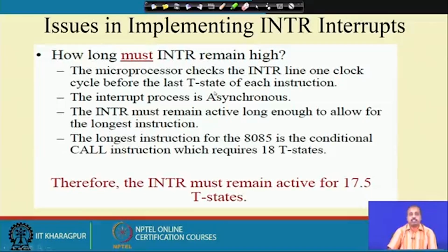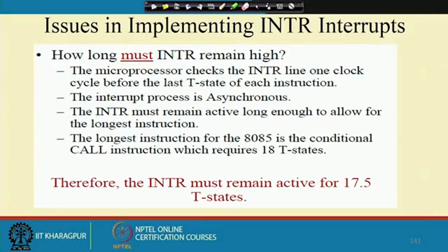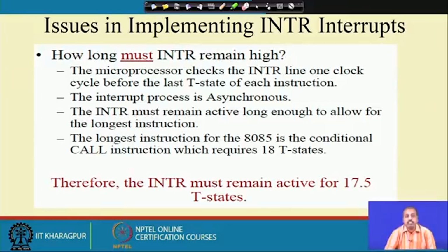Next, we answer the question: how long should the interrupt line remain high? This is a very pertinent question, because when you are designing a device to operate with the microprocessor, and the device will send an interrupt to the processor, how long should the device keep that interrupt line high so that it will be sensed by the processor? As we know, the microprocessor will check the INTR line 1 clock cycle before the last T state of each instruction.